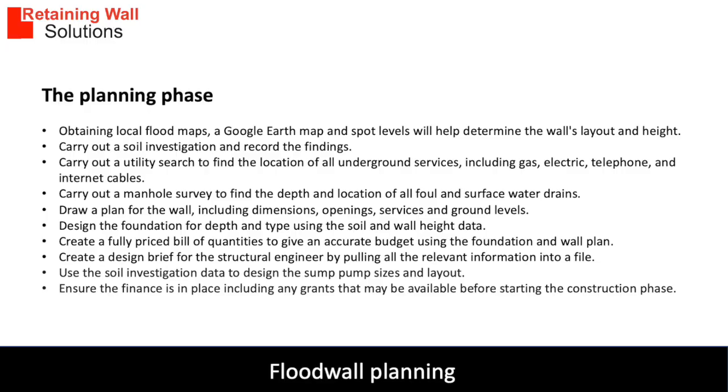Draw a plan for the wall, including dimensions, openings, services and ground levels. Design the foundation for depth and type using the soil and wall height data. Create a fully priced bill of quantities to give an accurate budget using the foundation and wall plan. Create a design brief for the structural engineer by pulling all the relevant information into one file. Use the soil investigation data to design the sump pump sizes and layout.